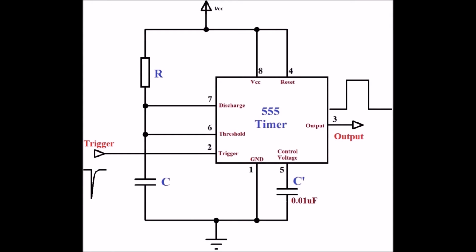This figure shows the 555 IC configured for the monostable operation. Under normal conditions, the trigger input is held high and the circuit is in a stable state represented by Q equal to low. Moreover, the BJT switch is closed, keeping C discharged, or the capacitor voltage equal to 0. The circuit is triggered by lowering the trigger input below VTL.